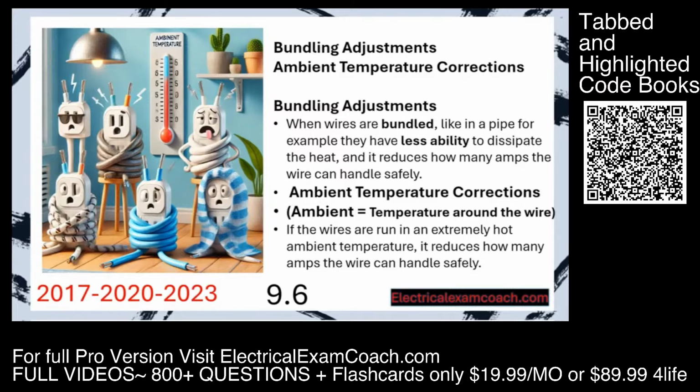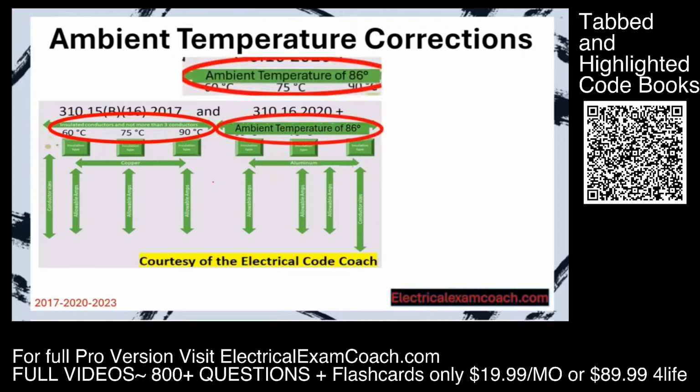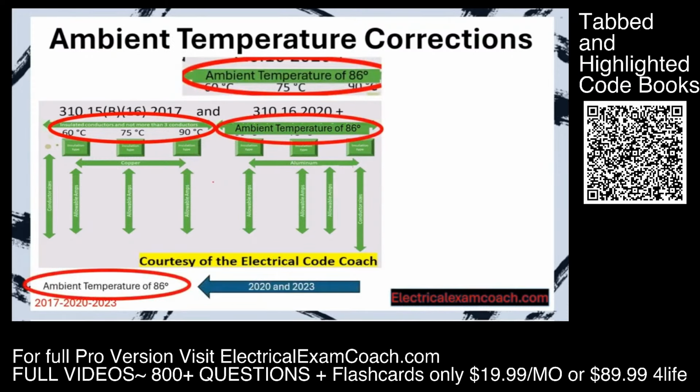Let's get to it. Let's take another look at our primary ampacity table. In the last lesson, we learned about the first part of the note that's at the top of the table, and it says that these values are true as long as you don't have more than 3 current carrying conductors. But there's a second piece to this. If you're in the 2017, it's at the top of the table. If you're in the 2020 and the 2023, it's at the bottom of the table. And what it's stating is that these values are true in this table as long as you're in an ambient temperature of 86 degrees Fahrenheit. Anytime you get outside of that ambient temperature, you're going to have to do an ambient temperature correction.